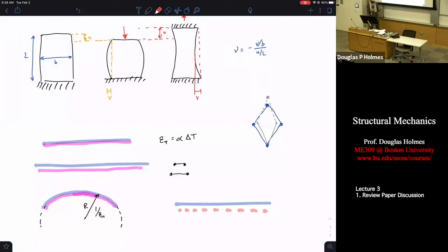That means you're heating up this end really fast. So this thing will still bend because the top of this metal is hot. Sorry, I guess the bottom, the way I drew it. Wow, that's huge. So the bottom of this metal would be hot, the top of it would be cooler, and so it'll bend to account for that. That's the differential heating. You've heated one side more than the other.